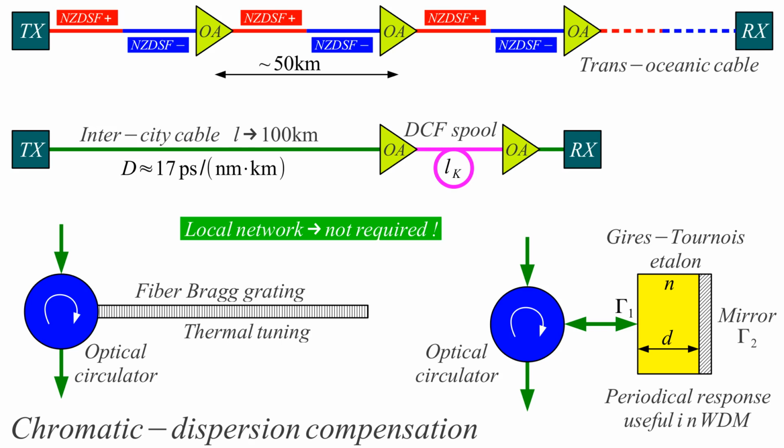In fact, the most popular erbium amplifier has a bandwidth of 4 terahertz, and this is our specification for this line, 4 terahertz bandwidth. This is the reason why we use this number elsewhere. These amplifiers have very good performance, very good signal to noise ratio, so it is possible to handle a line with 100 amplifiers in series and no signal regeneration under the surface of the ocean. This is the big advantage of having these very good optical amplifiers.